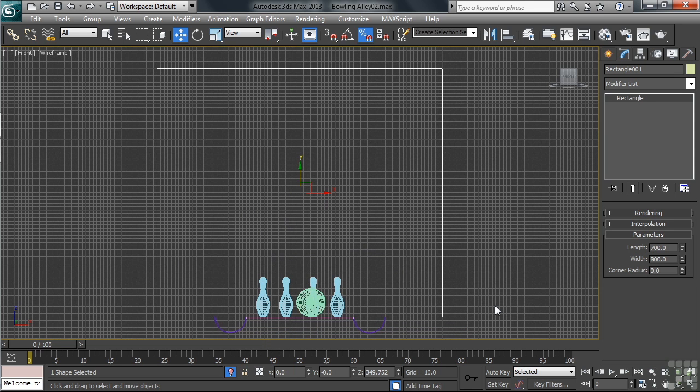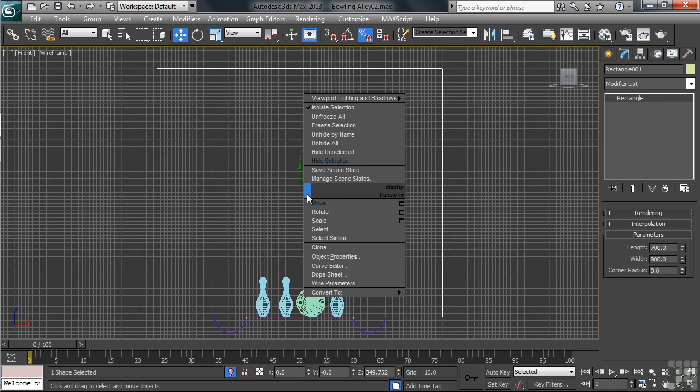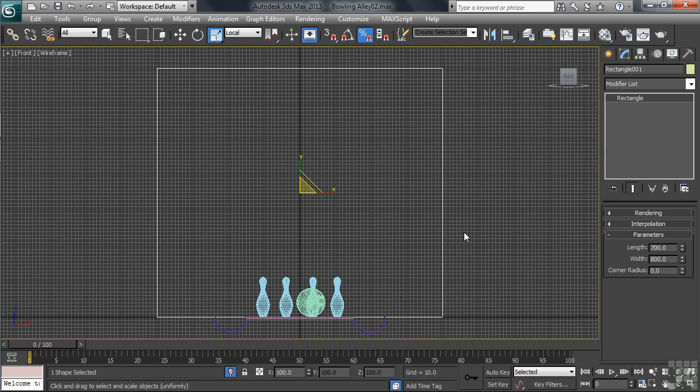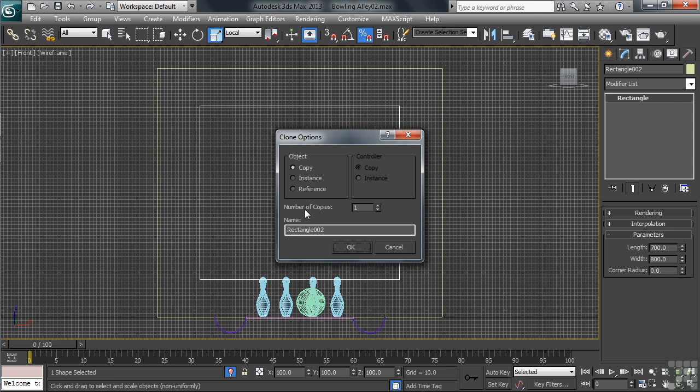Okay, now we're going to cut out the inside area before we convert this into a 3D object. Having the %snap toggle still active, let's switch over from Move to the Scale command. Holding down the Shift key so we'll make a copy, let's now fill in the empty diagonal bar on the Scale gizmo. As we drag to make our copy, look below the timeline, setting the % to 70. With that done, we can accept the options in the dialog as they are, simply clicking OK.